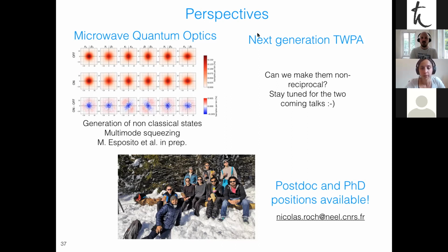Thanks. So I will answer in two steps. In principle, it should be the same. As soon as you have only the parametric process that you want, in this case the four-wave mixing parametric process I discussed, the dispersion engineering should not impact your noise properties. In other words, whether you have band engineering or not, your TWPA should be quantum limited. That's the first part of the answer.